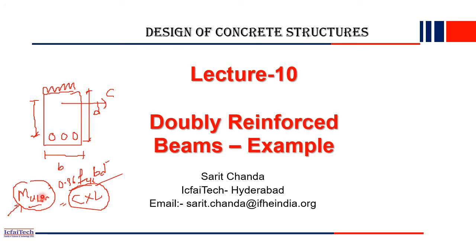But in reality, the depth of the beam is limited. We cannot increase the depth as much as we like, because very deep beams may not look aesthetically good. Based on the architectural design, they will tell us what the depth and the width of the beam could be. The width of the beam also depends on the width of the wall, so whatever the wall thickness is, we provide a similar beam thickness. So B and D also have limitations. We cannot increase B and D arbitrarily, so increasing them is not a good option.